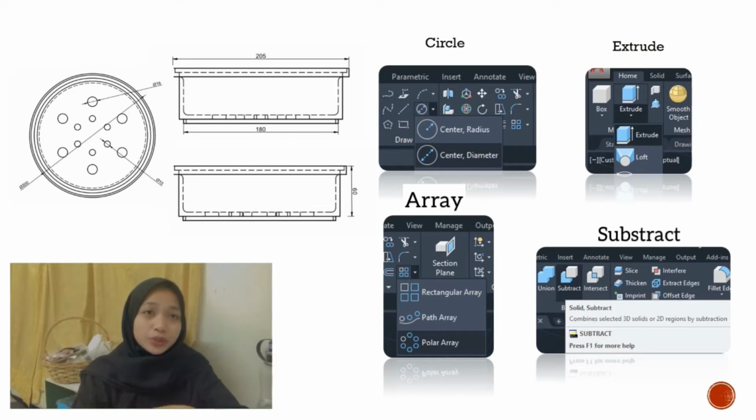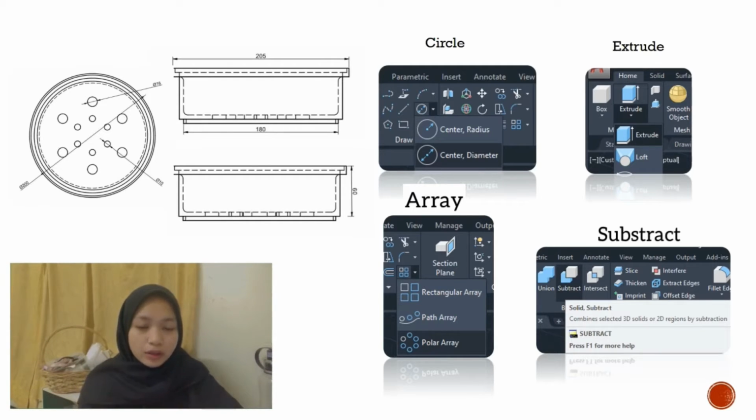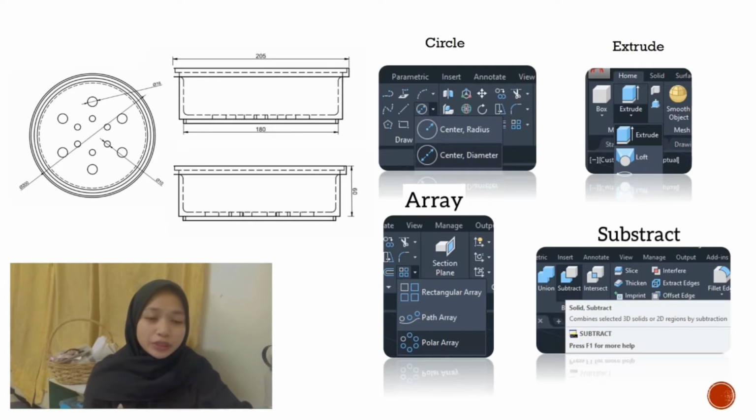Next, I will explain the steps of how to draw my drawing and the commands that I use. For part 4, first, I make a circle with a diameter of 190mm and then 180mm, which have the same center point. I use the command extrude to extrude the circle at 50mm height for the circle of 190mm, and 45mm height for the circle of 180mm.